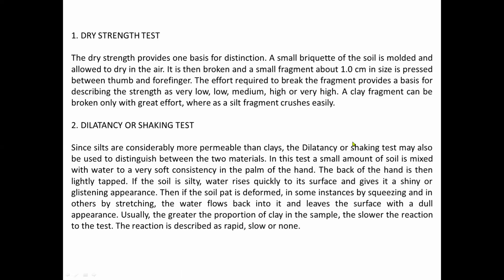Then we also have the shaking test. Since silts are considerably more permeable than clays, shaking tests may also be used to distinguish between the two materials. In this test, a small amount of soil is mixed with water to a very soft consistency in the palm of the hand. The back of the hand is then lightly tapped. If the soil is silty, water rises quickly to its surface and gives it a shiny or glistening appearance.